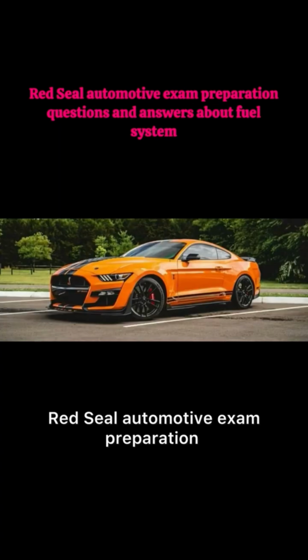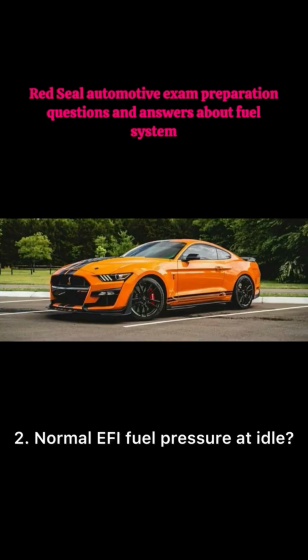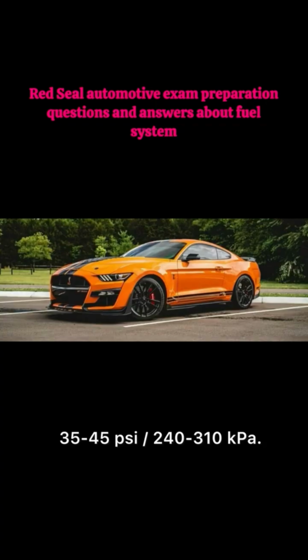Red Seal Automotive Exam Preparation. 1. What does a fuel pressure regulator do? Maintains steady fuel pressure at injectors. 2. Normal EFI fuel pressure at idle. 35-45 psi / 240-310 kPa.